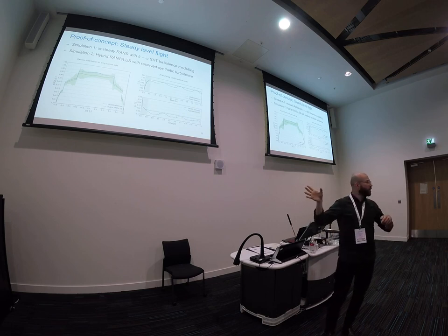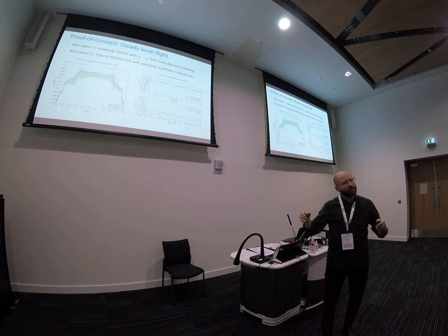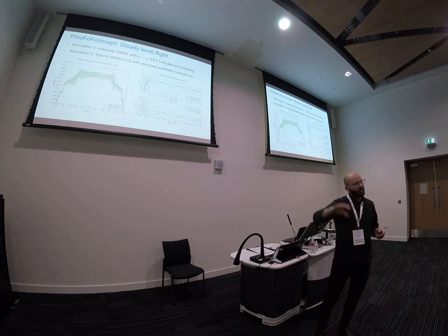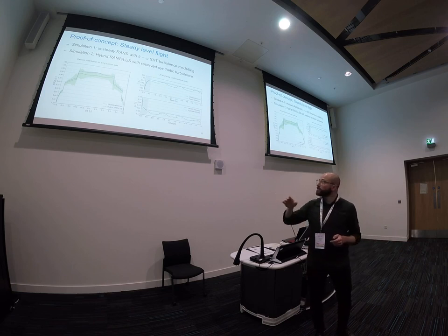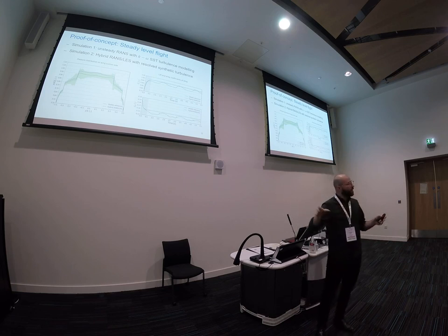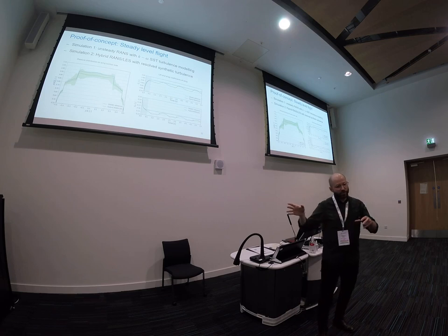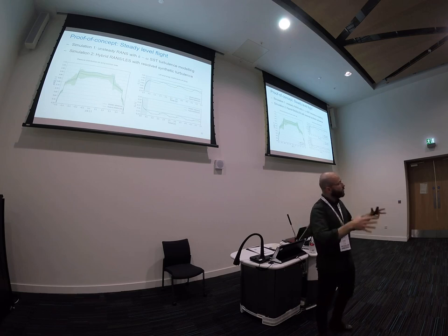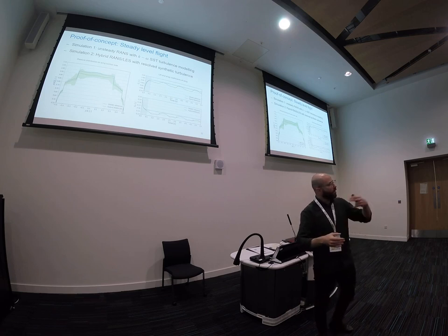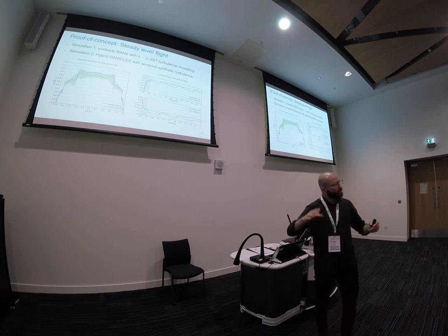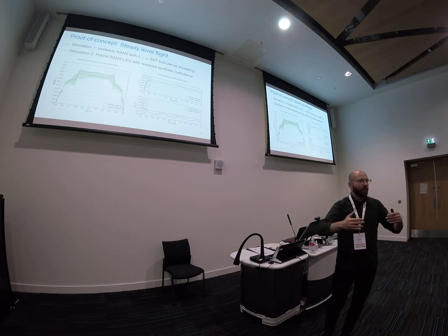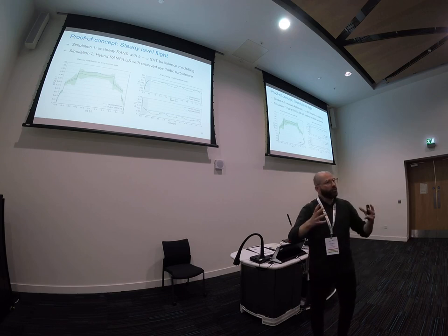We have the green line, which is the hybrid simulation, and blue, the reference simulation, where we have this pattern of, let's say, kind of sine wave. And this pattern is actually seen here because the Mann box that we use enters 3 times the domain in this specific case. So actually this fluctuation that you see is the reoccurring passage, let's say, of a certain flow feature from the turbulent wind field.